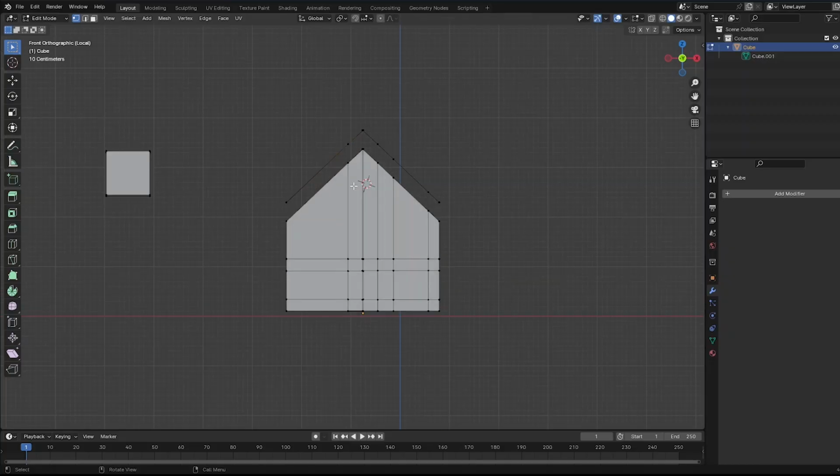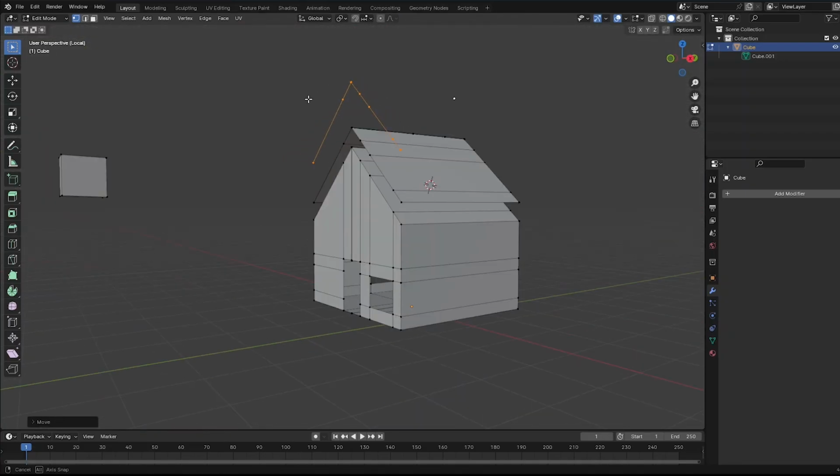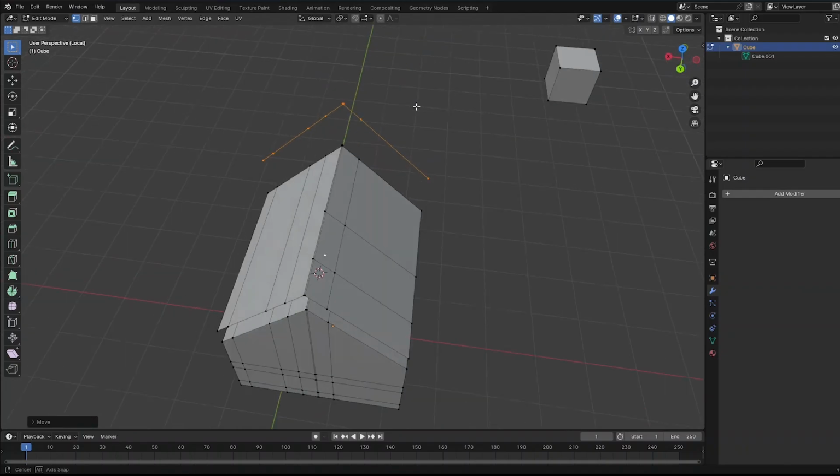Let's say I keep it on one so that I get the front view. Press C and then select the top parts of your shed. And then you can just press Shift and D to make a copy and press G to take it out. Shift and D, duplicate it, press G to take it out. Right click over here, Shift D, G to take it out of your whole area. There we go. And after you're done, you can just check the whole thing out.